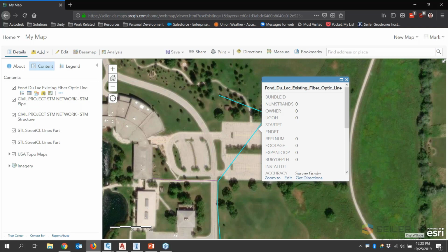There are a couple caveats here. The process does not work with pressure network parts at this time. So most of Civil 3D objects are covered: surfaces, alignments, gravity sewer networks, parcel data. But at this time, not pressure network parts. So if you're dealing with water main GIS data, bring it in as feature line.